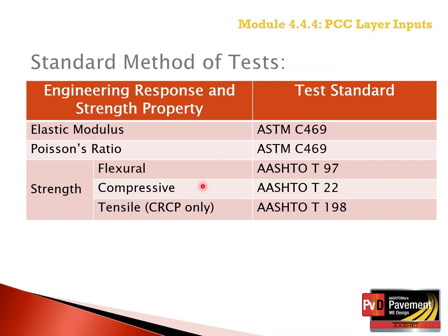Determination of these PCC layer properties will be further discussed in the next section of this module, because during the structural design, which can be 1 or 2 years prior to construction and contractor selection, the PCC mixture is unavailable for actual testing in the laboratory for most design projects.